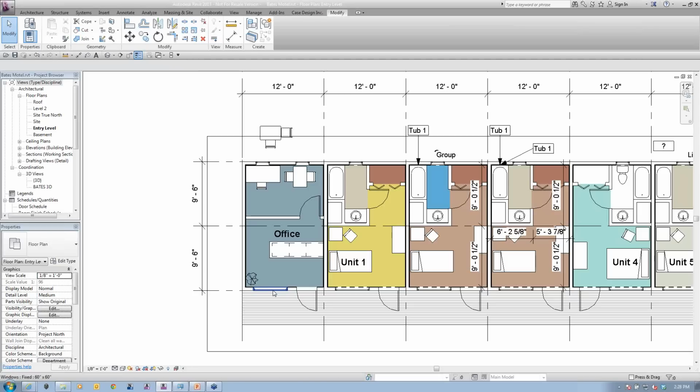There's other things that inherently I don't like about the MEP portions, as far as I have to host the ceilings, and I have a lot of issues with ceilings that have to be either done with roofs or with walls that ceilings just aren't functioning well with. But a lot of things that have been a great workflow with the MEP portion is now I can reconcile things that are unhosted, which is a great workflow that we did not have in the past. You just kind of lost everything in there. And now at least it becomes unhosted, we can rehost it.